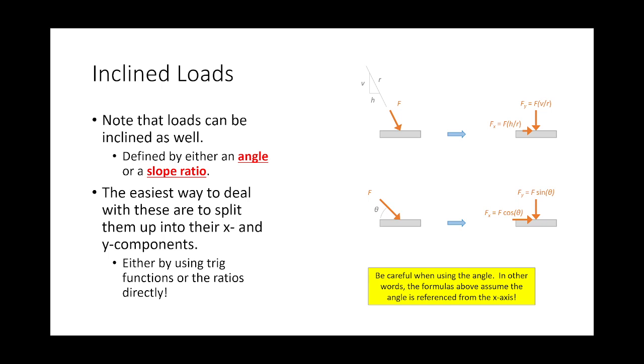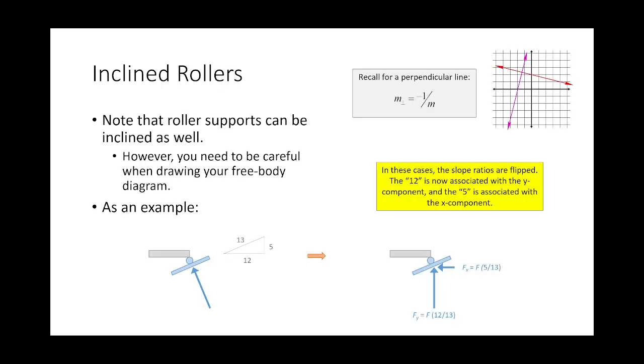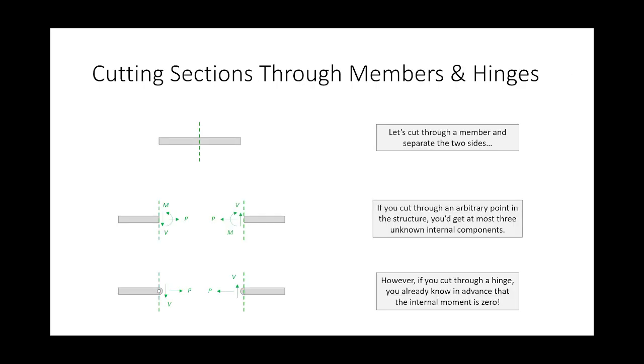For instance, if you have a beam and you have an inclined load, only the vertical component of that load contributes to the shear diagram, right? We were talking about transverse shears, just as an example. Inclined rollers, make sure that you can handle that. And again, to be clear, I'm not going to try and get too far down the weeds of what we did on exam 1, but I just want you to be thinking about this stuff.